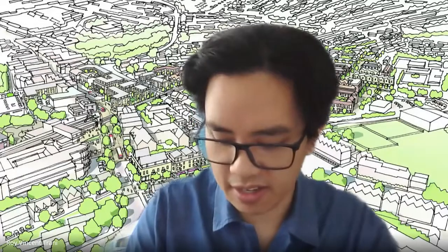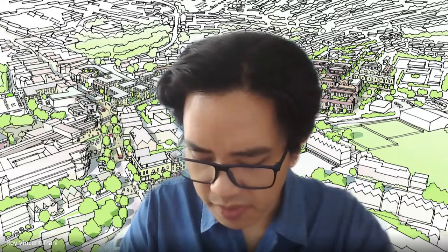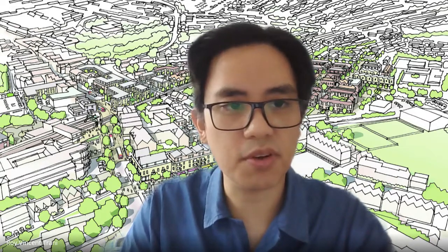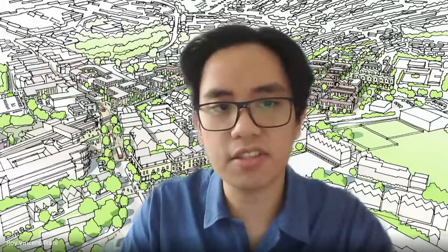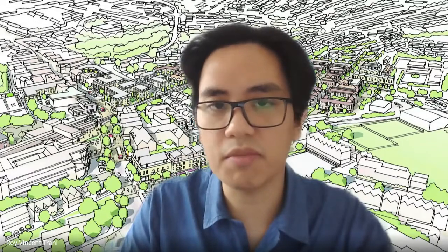Thank you. Okay, before you go, don't close the slide yet. Some questions over here. Let's go back to the turning radius. Just to note for everyone, this is also part of the recording, that's 6.5 meters inner radius. So that's B, the inner radius. Yes, sir. And then on the outer radius, that's A, about 11.58 to 12 meters. That's for 90 degrees, and there's also a 180 degrees.